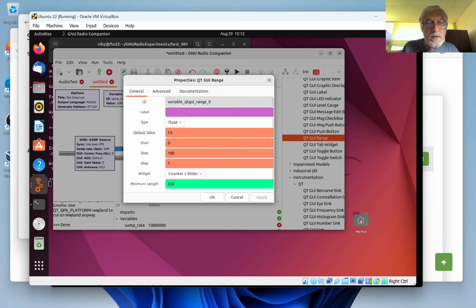So as a default value, we could choose say 100 megahertz, and we could start at about 80, and we could go to about 120. Okay, and we change this in 0.1 megahertz and 100 kilohertz steps, and we have to give it a name. So this is going to be the carrier frequency, so I'm going to call it FC.